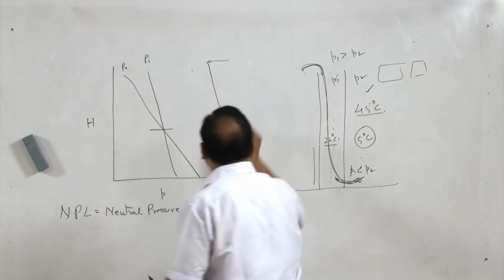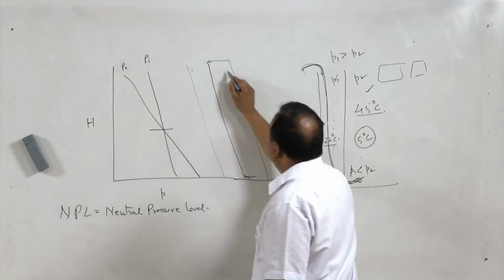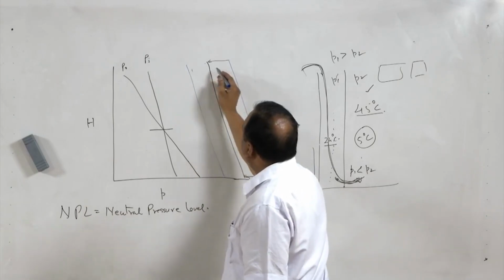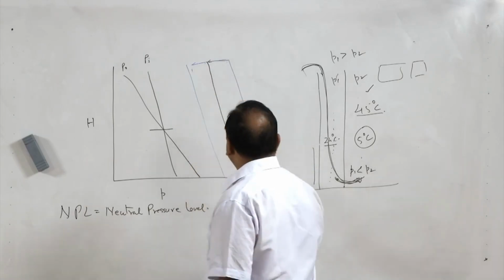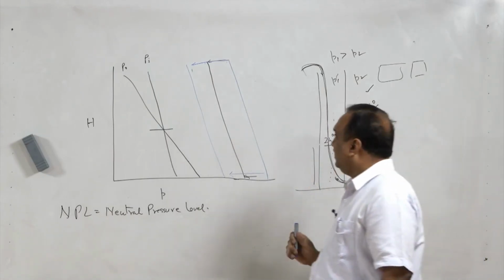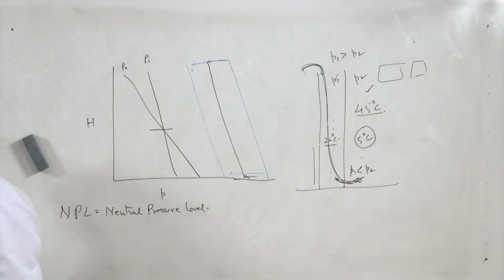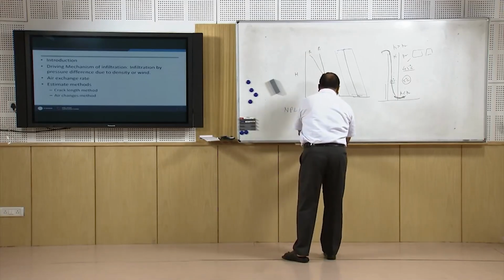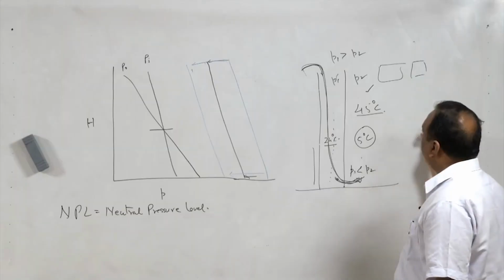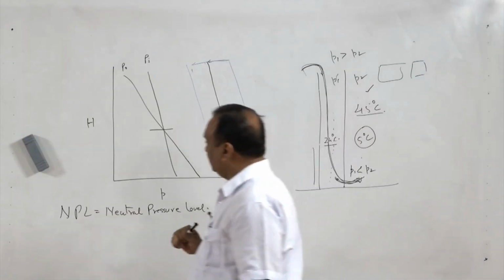If I show the pressure of air, it is going to be windward side and leeward side, this is negative pressure, and air will be flowing out of the building from the top to bottom. So air movement in infiltration is also important. We cannot always say that the movement of the air will be like this. Suppose the wind velocity is high, then air will enter from all the possible points in the building.